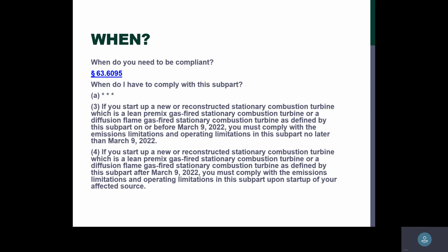So there's the MKS Multi-Gas 2030, which has been probably the predominant FTIR used in the natural gas industry for the last decade and a half. When the Quad Z MACT rule came out, we were all in a rush to go get FTIR analyzers so that we could measure the formaldehyde.